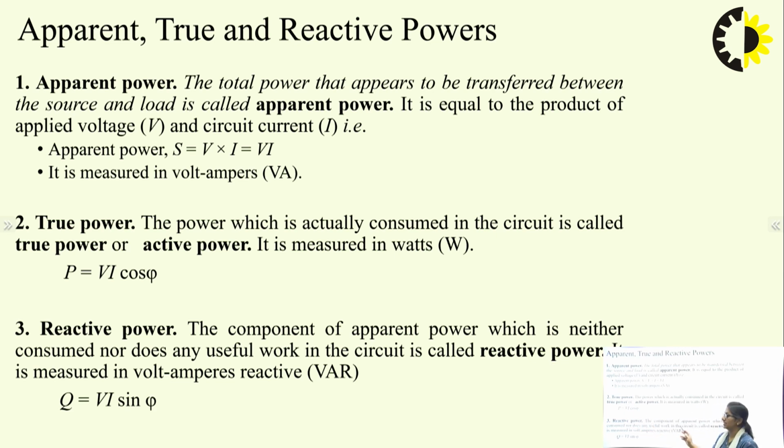And lastly, the reactive power, the component of the apparent power which is actually neither consumed nor does any useful work in the circuit, is called reactive power. It is measured in VAR, volt ampere reactive, denoted by the letter Q, given by VI sin phi.